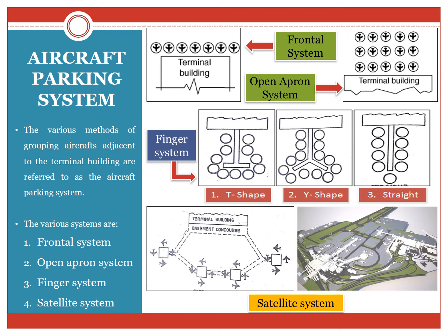Moving across to the finger system. Now, what is a finger system? See the figure closely. In this system, the connection of the aircraft to the terminal building is achieved through types of piers or fingers. Now, the piers or the fingers can be fenced, an open walkway, or a closed structure, single or multi-storied. They can be straight, T-shaped, or Y-shaped.